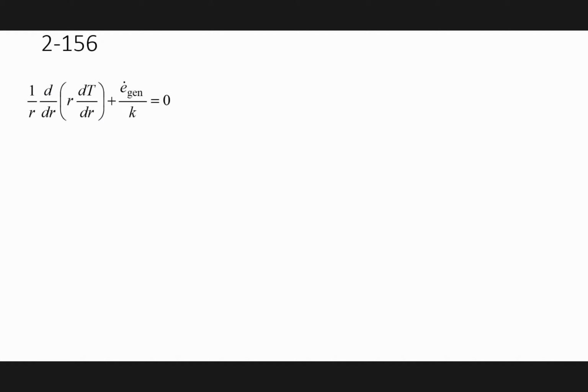But if you look at this equation, this generation is per unit of volume. Okay, then we have 25 kilowatts. This is per unit of volume. Therefore, now we have two boundary conditions: at r equal 15 it mentions what the temperature is, and at r equal 20 it also mentions what temperature. Therefore, we integrate this equation. This is one boundary condition that we have, and this is the second boundary condition.